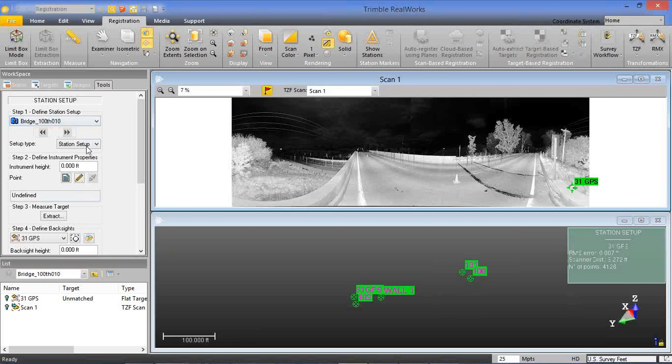Once you perform a single station setup, you can make your way through other stations and also perform their setups so that they align for the total project. In this example, I've only got one scan that I'm going to show. And a couple things you ignore. 1, ignore the residuals. 2, ignore the geometry used to perform this resection. I know they're both not good, but I didn't have a good data set to show this.